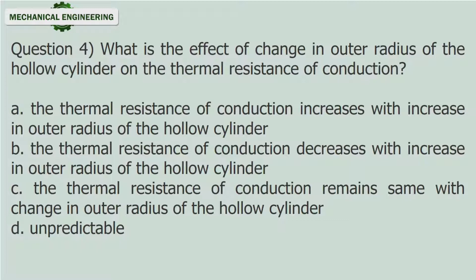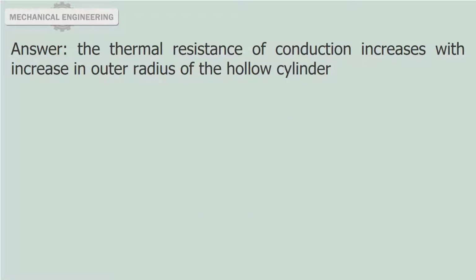C. The thermal resistance of conduction remains same with change in outer radius of the hollow cylinder. D. Unpredictable. Answer: the thermal resistance of conduction increases with increase in outer radius of the hollow cylinder.